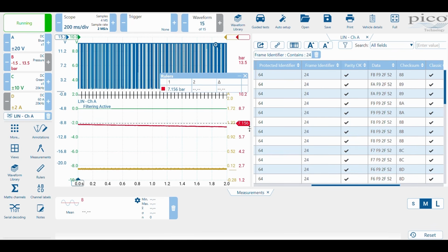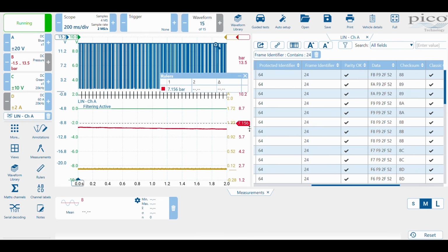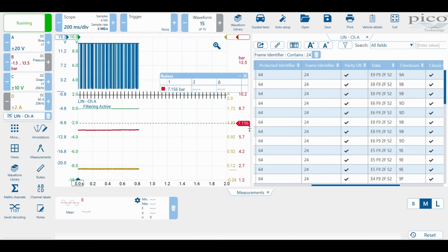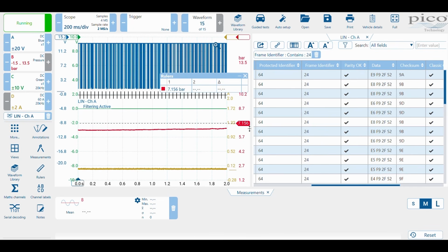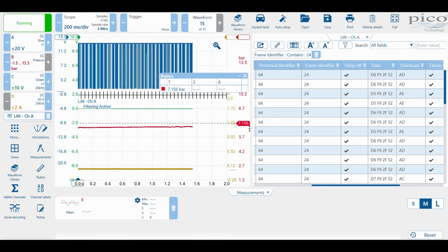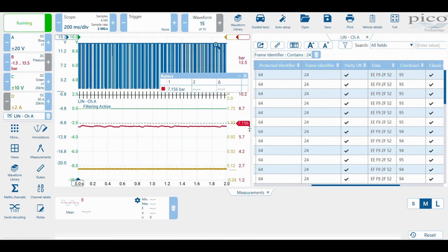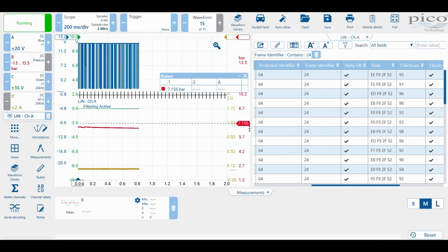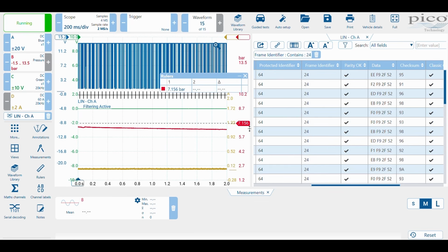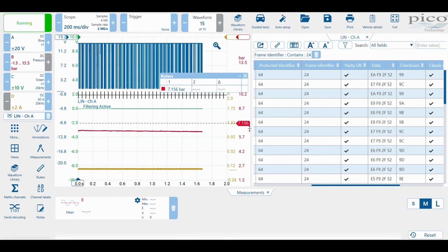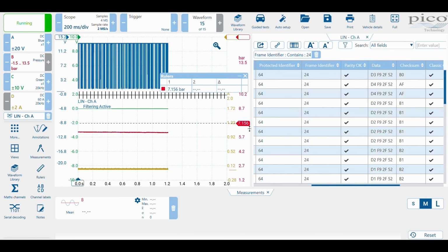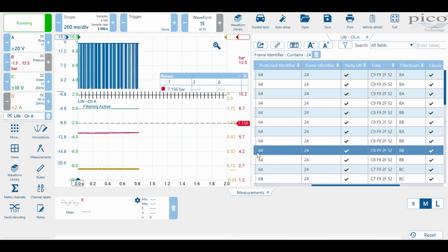So food for thought when you're actually doing this, be aware that 2 bytes could be used to denote air conditioning pressure. But we've gone back to F9 again, which is interesting because when it fell, it was F9 in the second byte. But we'll work with that. And then from that, we'll see, based on those 2 points that we've obtained, whether we can apply a scale and offset and work out what those pressures are.